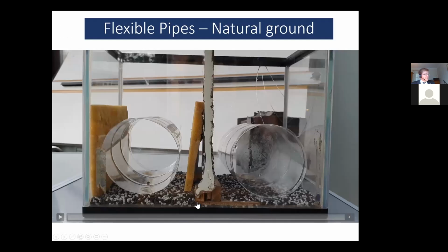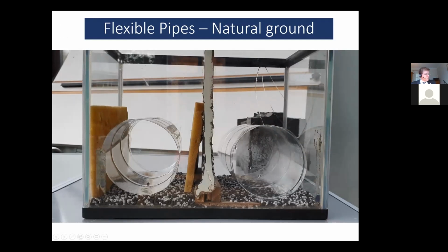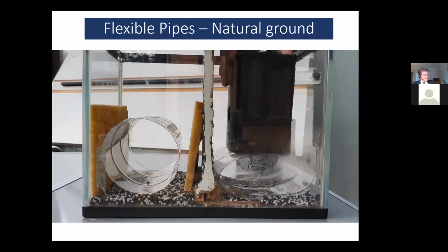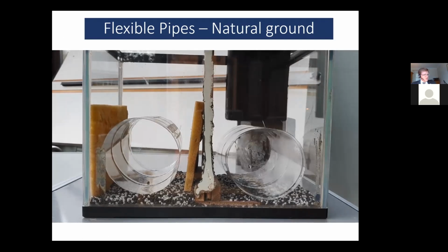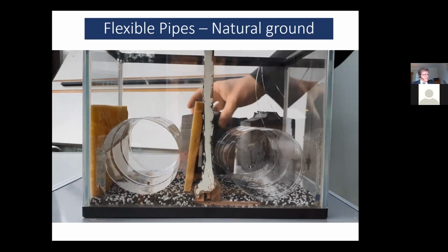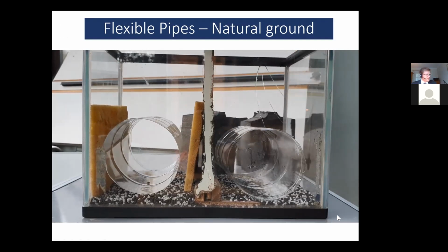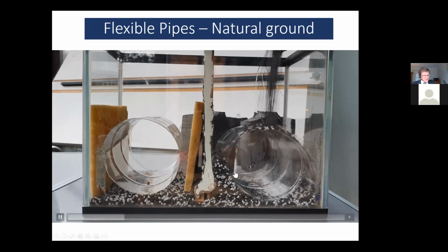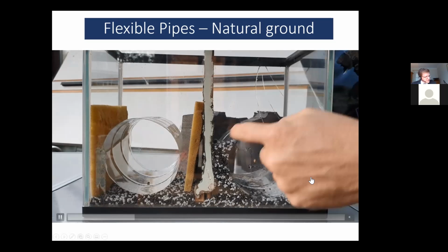When you get onto the flexible pipes, I'm just showing this video. Now what I'm going to do is drop a block of plastic onto this flexible pipe. This flexible pipe doesn't have a lot of inherent strength. So there you go. It's a big block of polyethylene, a sample from a 75mm thick pipe as it happens, but it works as a good block. What I'm going to do is pour embedment around this now. This is a class S1 embedment, single size gravel, and it flows beautifully right round and right underneath the pipe, as I'm going to indicate.